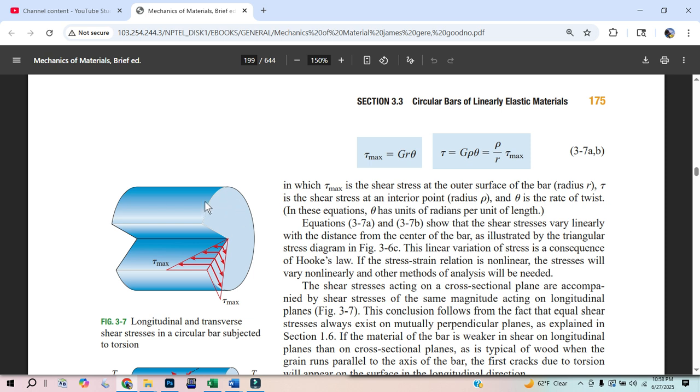And so visually, if I'm still going back to this as a hollow cylinder that's one molecule in thickness, I'm just going to put a force on every molecule, perpendicular to the direction of the radius, or tangent to the circle, and each of those forces are going to take this disk of molecules and torque it. Those forces are a distance of the radius away, so each of them adds up to a total moment on this cross-section, and this other cross-section over here has to resist it. And so that's what we have.